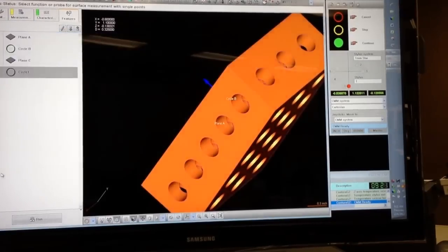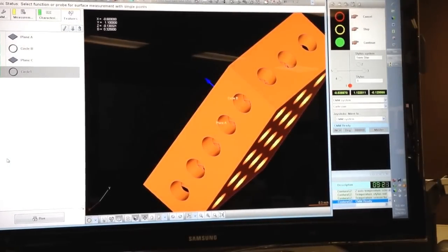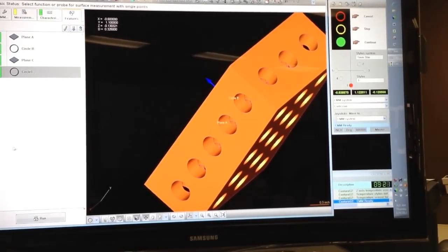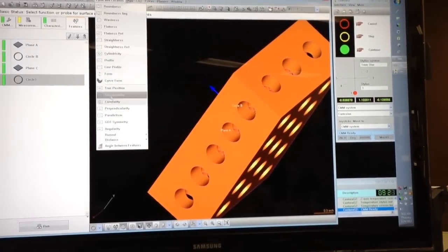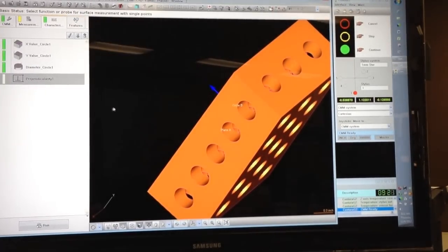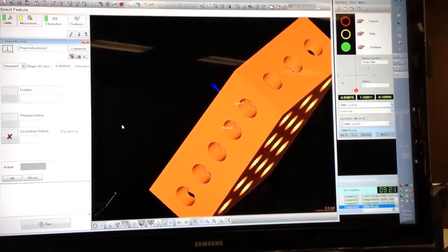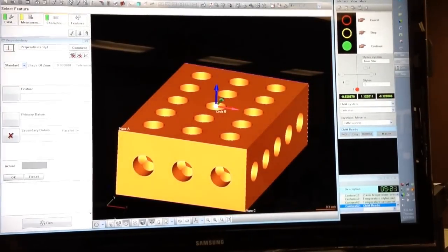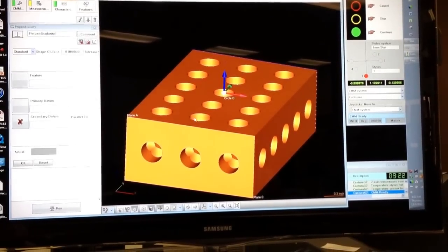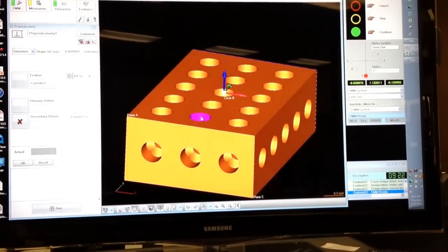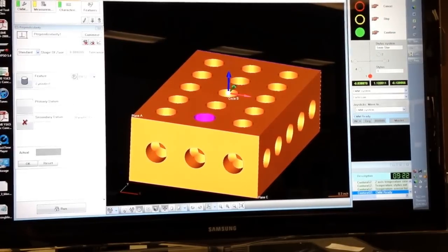and then we'll output y and diameter as well. The second challenge, the perpendicularity of a cylinder front and center to the primary datum plane. So I'm going to start by going and getting the perpendicularity characteristic. We'll see it has inserted itself in the list here. I open up the perpendicularity characteristic, I switch my CAD programming tool to extract features, and I extract the cylinder from the front center. We see that that cylinder automatically plugs itself in over here.